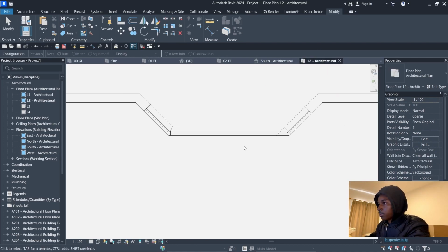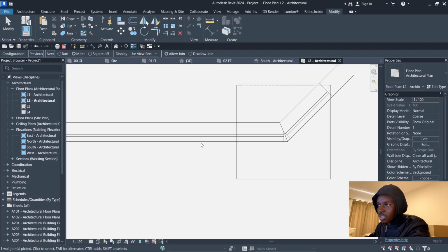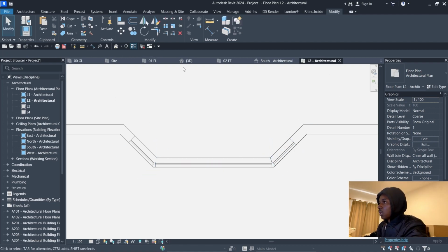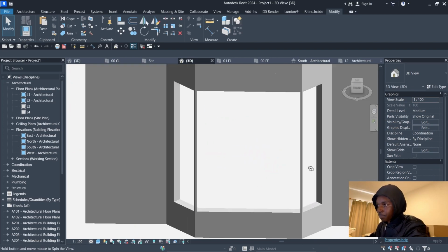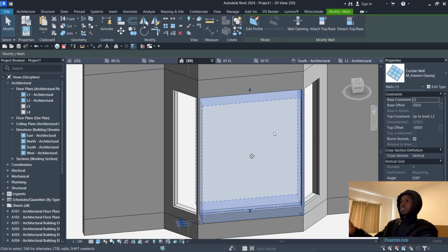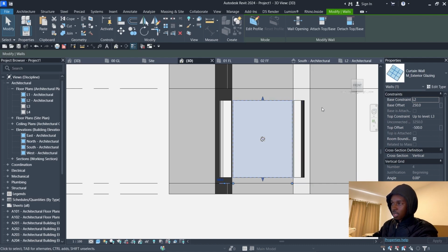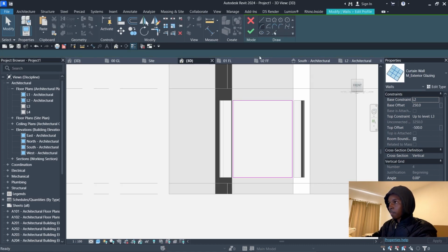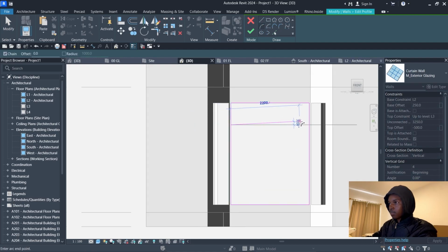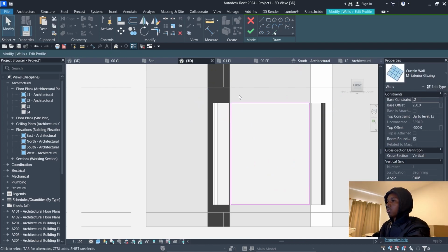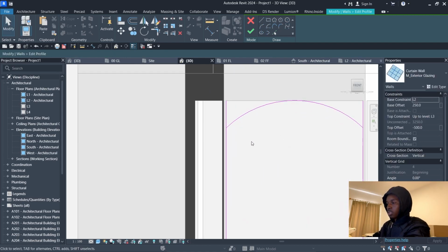Go back to level 2, select this, and then miter this too so that it will be the same joint. So I can escape from that tool now, come back to 3D. Now we have this. So from this I can just now edit profile. This should be family territory for you guys. So edit profile and then change that. Okay, let's do that now. Let me drop it 7. Is it? Okay, let me drop it 500 here. Yes. Alright. So we can delete this, trim this.